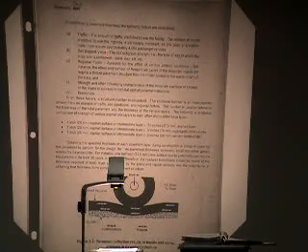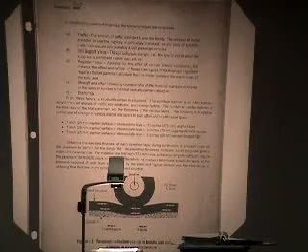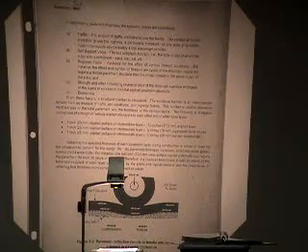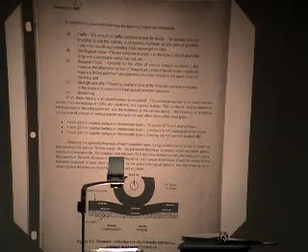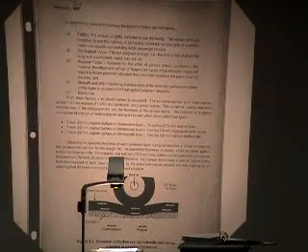And then soil support value, that's related to the subgrade. Obviously, some soils have stronger strength values than others, so that comes into play. A regional factor is applied: with the same exact conditions for traffic and subgrade strength and so on, pavements in western North Carolina will be slightly thicker than pavements in central and eastern North Carolina. Why would you think that's the case?